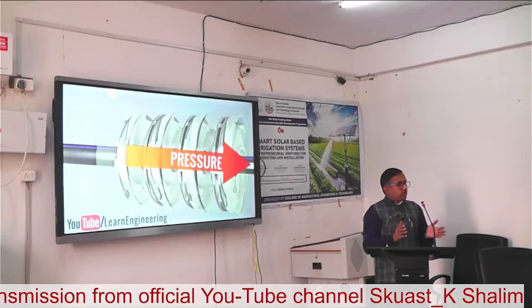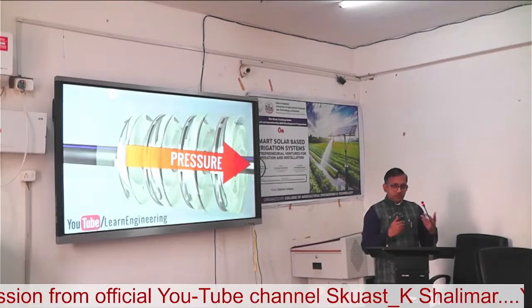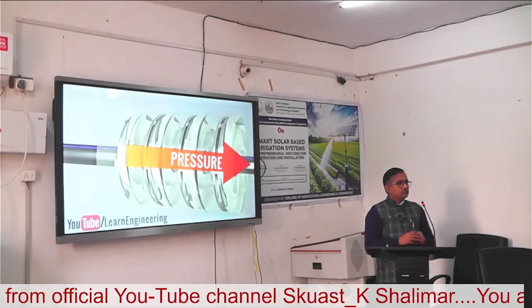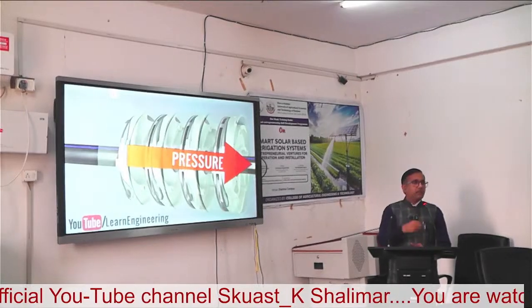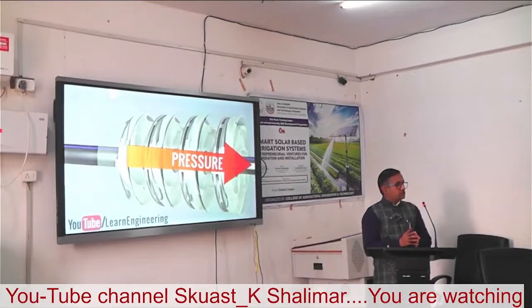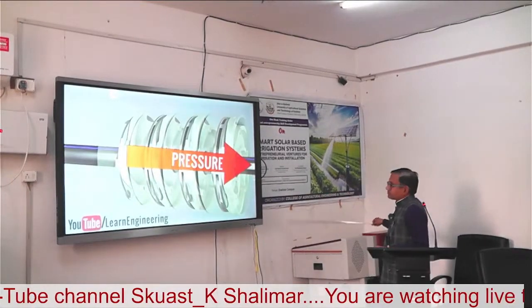If you increase the number of impellers, obviously more input power is required. The PV panel size is more. If we are using a small head and small discharge, then the number of impellers is less and the PV panel is also less. So as per your requirement, as per the conditions and discharge, we can use the number of impellers here.